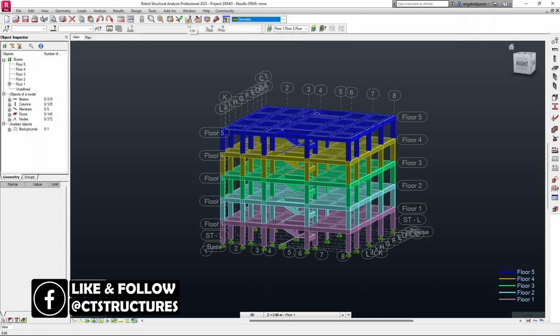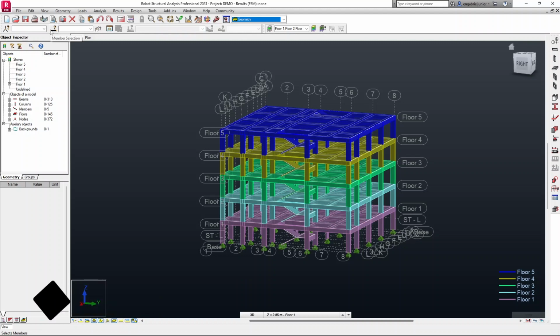Next up, we have the selection bar, which is at the side here. This allows us to make customized selections of components of the model. For example, we may need to select elements on different elevations, different section parameters, etc. On the side here, we have the story definition bar. Now this allows us to edit story information, and this option is only available in the building design template that we have chosen. It is quite useful when it comes to selecting elements within the model.